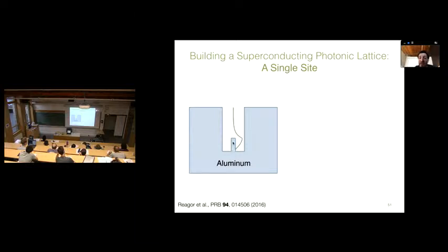The way you should think about this 5 gigahertz resonator is that we've added a center pin. So this bottom piece is basically like a coaxial cable, where coaxial cables are happy to propagate light whose frequency is well below the spacing between the center pin and the outer shield, because the signal can propagate on the center pin. So now you should think about this as a coaxial resonator waveguide where the center pin is shorted to the shield at one end and open at the other end.